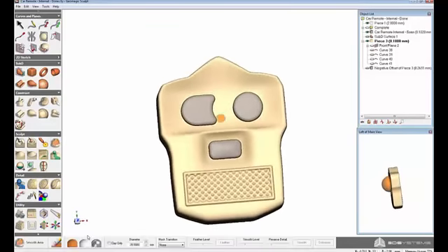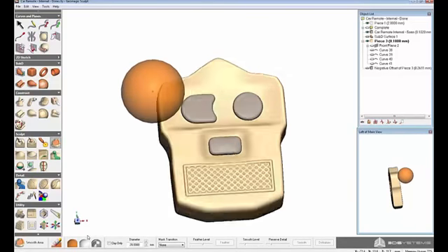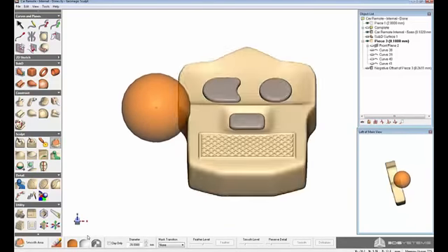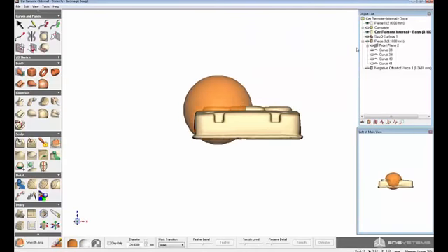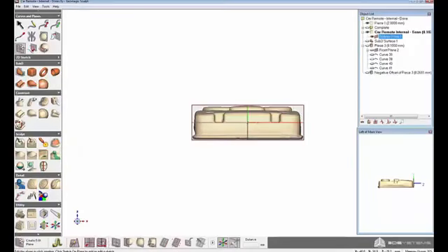But we still need to make the cutouts, right? So we have the scan of the buttons and the way they look. Maybe this particular model, we don't have the CAD design too, so we can't import that in. So we scanned it just like I showed you. And now we need to take a cross section of those buttons and use that to cut out the tool. And as you expect, it's pretty dang easy to do that. So let's hide the outsides of the housing, and let's create a plane that's going to cross section right there. Just a few quick buttons.